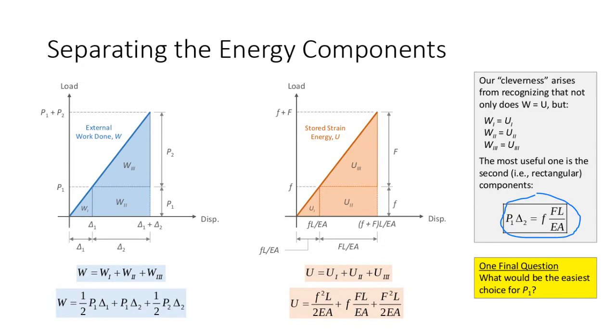It may not seem that powerful, but it really is, because I can find the deflection due to this set of loads by using the results from analysis 1 and the results of analysis 2 separately. And on top of that, I can find the deflection due to that second set of loads when the structure is subjected to any amount of P1. It doesn't really matter what P1 is as long as I track that appropriately.